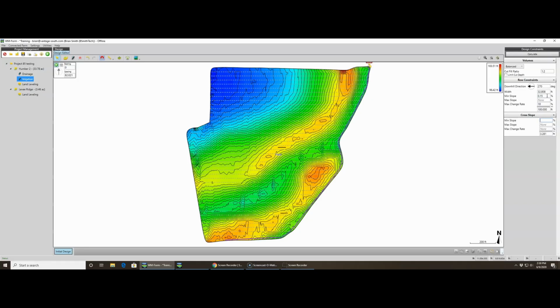Minimum slope, maximum slope, the cross slope. This will let the cross slope fall right or left of the downhill direction. Okay, so we go minimum slope right and left. I don't want anything more than, let's say, 1/10.5. That's going to give us quite straight lines.